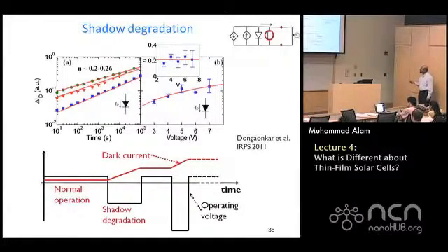And you can show that as a function of time, if you put things in shadow, this is going to degrade significantly. The dark current is going to degrade significantly because one of them is in the reverse bias. And not only will the output power temporarily go down, but that shadowed one, which you are thinking of as just resting, will essentially be in the reverse bias, and a significant amount of defect will be generated. Very counterintuitive. Right? Shadow, you think good, it can rest, but not when you just take one of them and don't give everybody else rest as well.